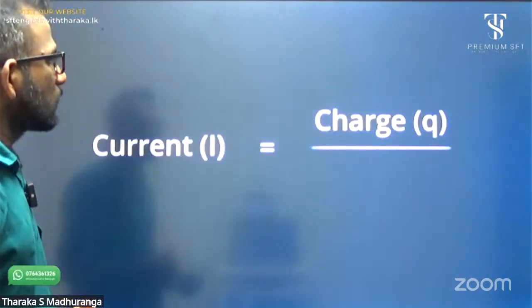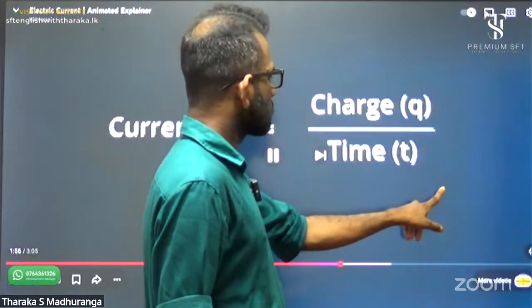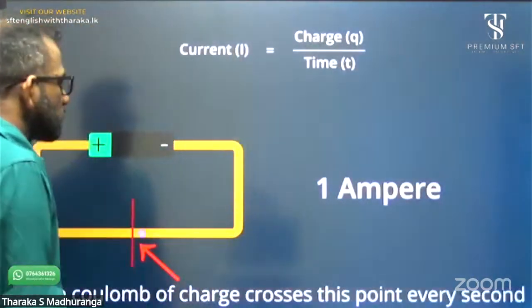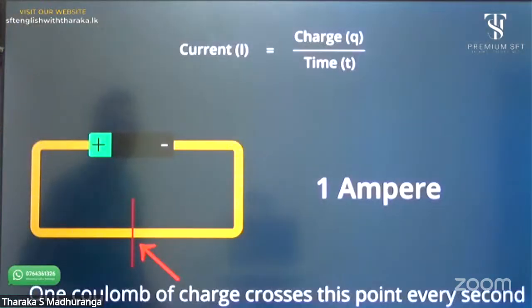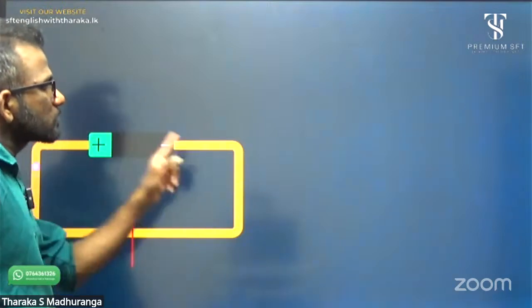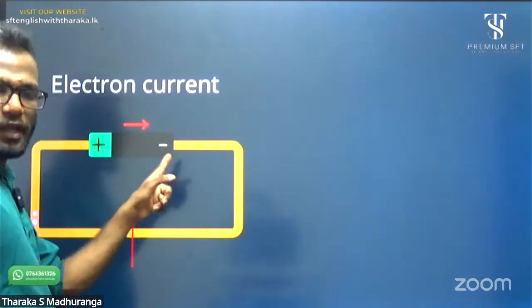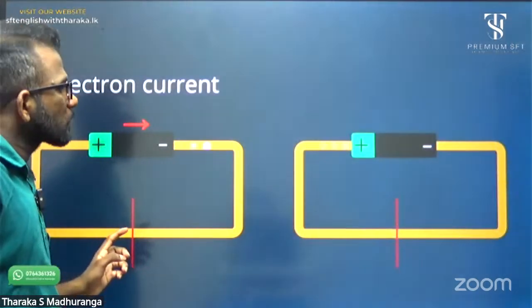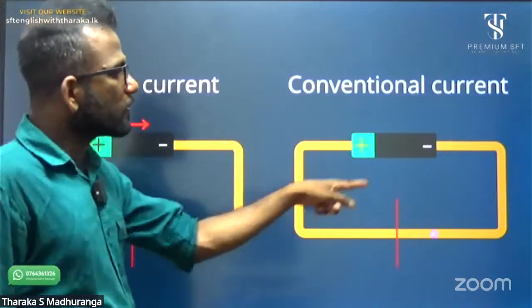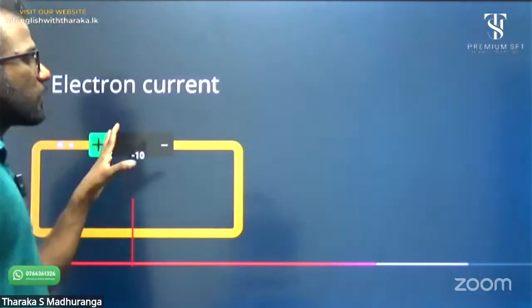Now mathematically, current, represented as I, is the charge. Okay, these equations we can discuss later. A current of 1 ampere means 1 coulomb of charge flows every second. Before we move on, see the direction. When we talk about the flow of electrons, they actually move from the negative terminal to the positive terminal. Negative to positive. Historically, the conventional current was defined as moving from positive to negative. This is the current direction. This was set before we understood electron flow. So okay, clearly understand the direction.